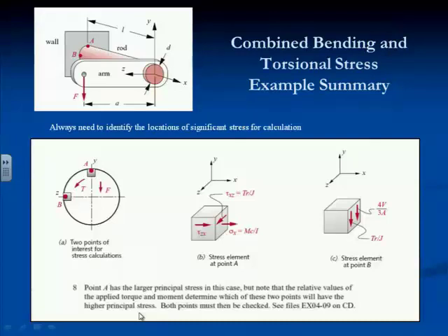Before we change topics, everyone okay with this? This is a very, very important concept to understand because you're going to run into it over and over again. You have to consider where in the physical system are the loads the greatest. Cantilever, moments at worst at the root, right? If it's simply supported, the moment's worst someplace in between the two supports. You've got to figure that out. And then cross-section, where the stress is the worst.